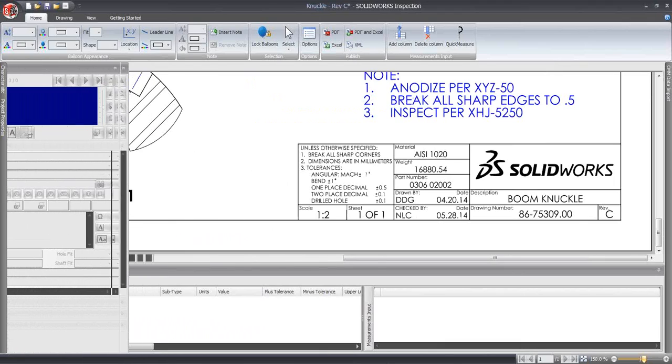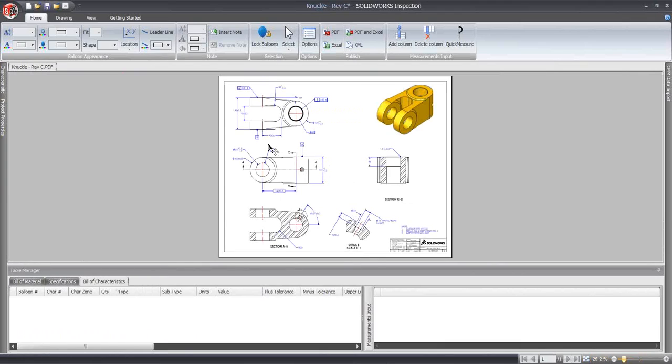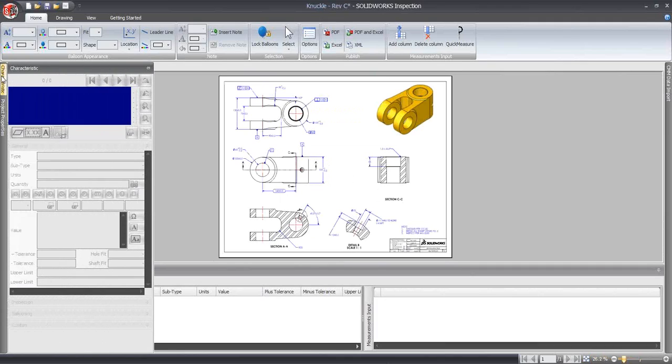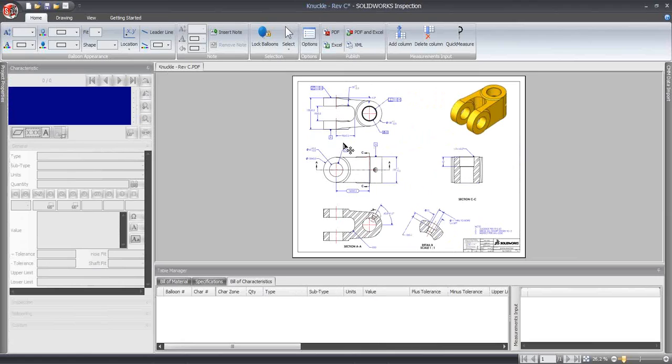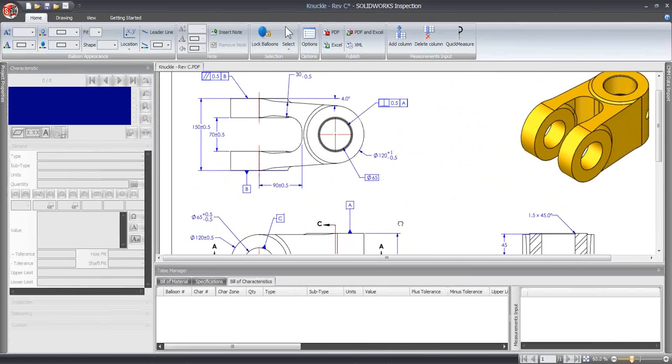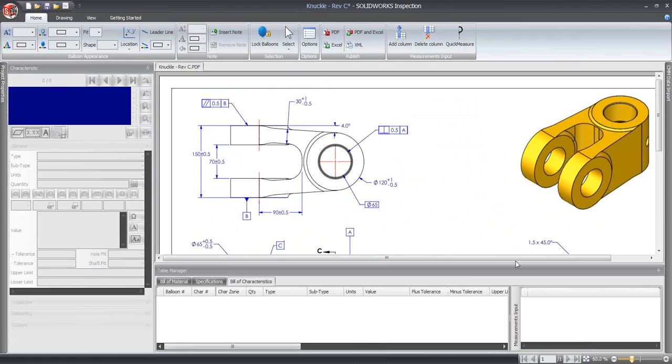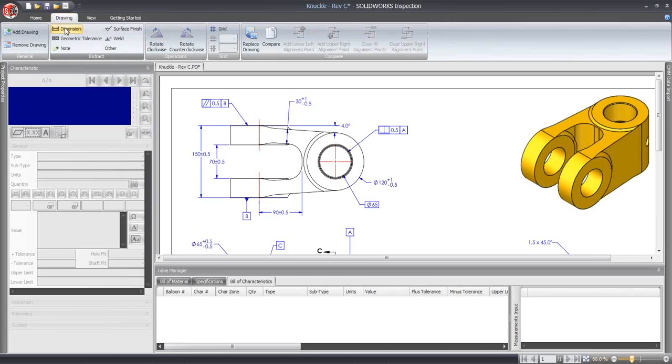Next thing that I want to capture are my dimensions. So let's see how we can do that. For that, you need to go to the characteristics capture window. I'll just go on this. Let's zoom into the drawing. As we know, it's a PDF drawing. Again, I would like to mention, we'll again make use of our OCR tool. So you can just go to the drawing. I want to capture some dimensions from here. So let's capture this dimension first.